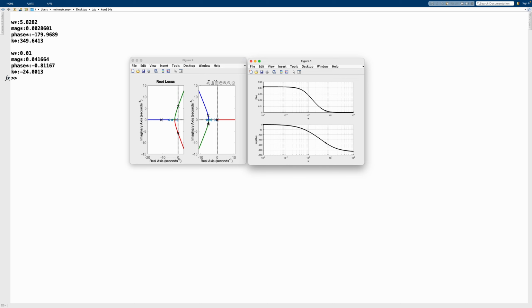At a certain point, for example, at this point exactly, or maybe this point here, we will have zero overshoot, because all of the poles will be on the real axis for this system specifically. That tells us that we will have a certain point where we will have zero overshoot. We know the point of 100% overshoot. So we need to come up with a way of ratioing it so that we can say, okay, this point here should be the overshoot that I want.